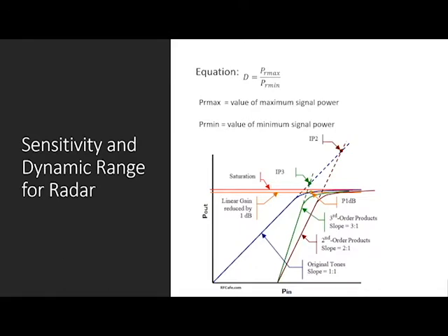Dynamic range is a key parameter in electronic systems, but one that is often difficult to compare at the component level when trying to design a system for optimum performance. It is a specification that is often defined at the upper limit by a conceptual parameter known as the third order intercept point. Typically expressed in decibels or dBs, dynamic range is the ratio of the highest signal level a circuit can handle and the lowest signal level a circuit can handle.